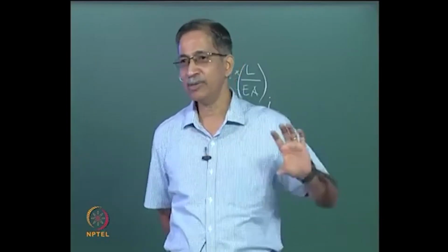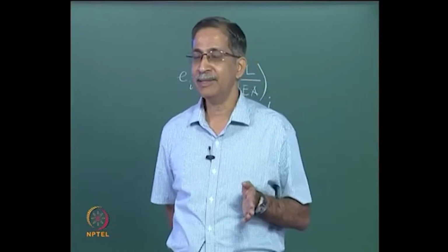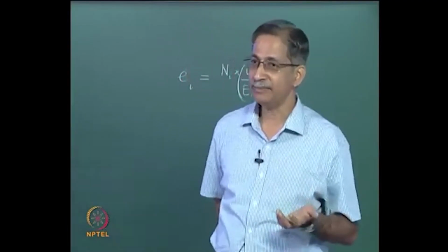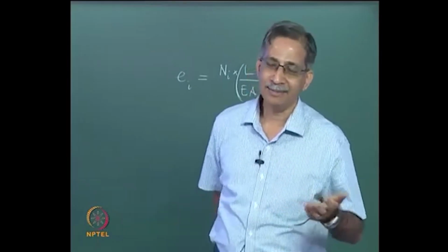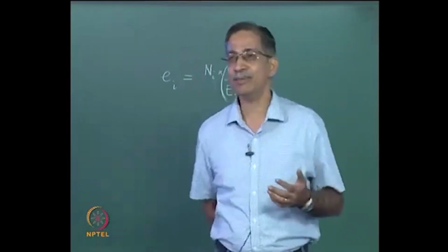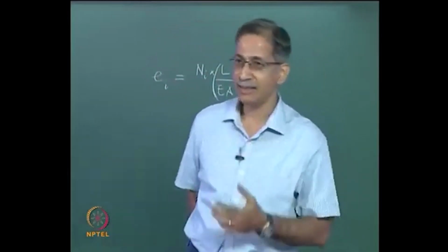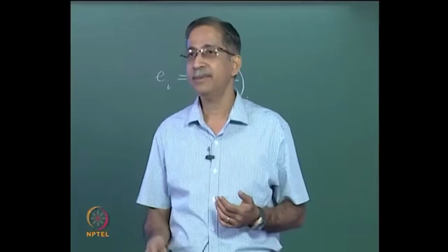That you get from the equivalence with the beam when you do method of section. So we should prefer the bars going into tension. Why? Because then you have problems associated with buckling, and the size of the member has to be larger and so on. So these are important points to note.